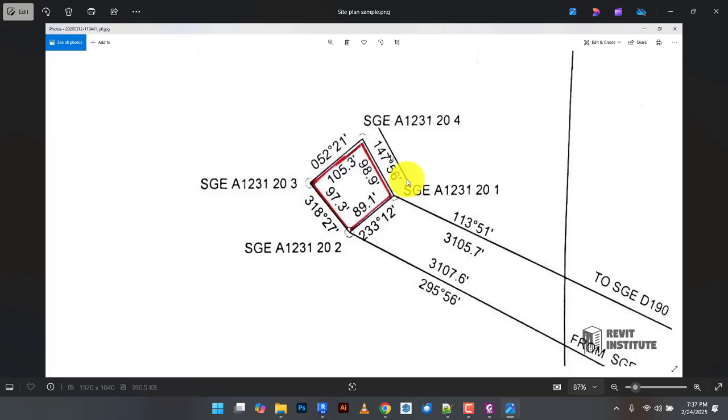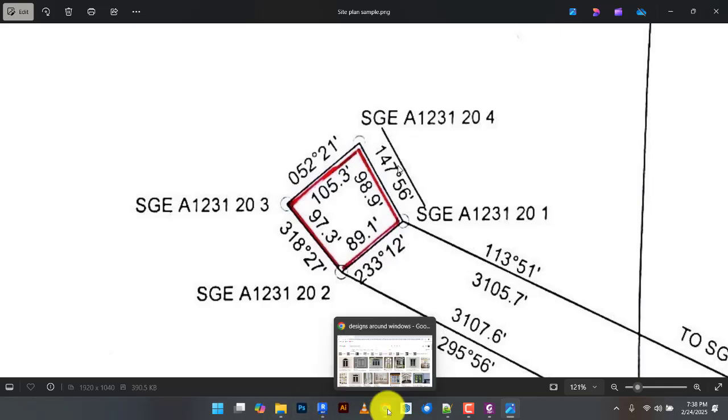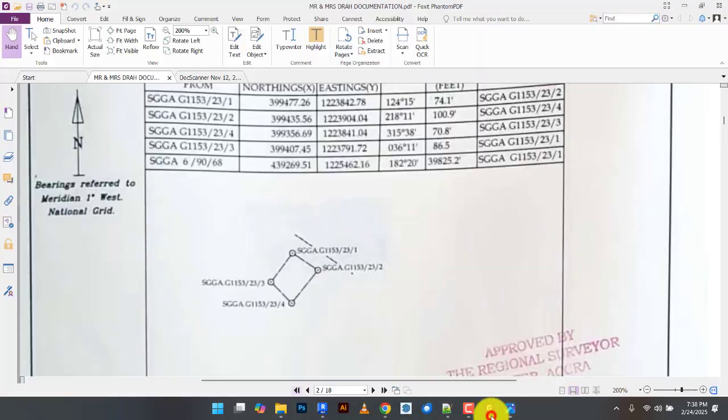No. The line here. Does this one have the line? It's an offset, but it means something. See, this one also has it here. Sometimes it's even two. There'll be another one here. Sometimes it's three. No, you are getting close to it. So it's a road. It tells you this is where the road is relative to the land, so that you can inform your positioning of the building. Right?